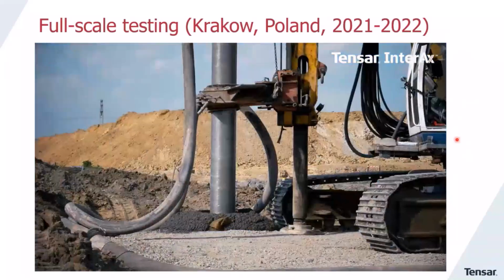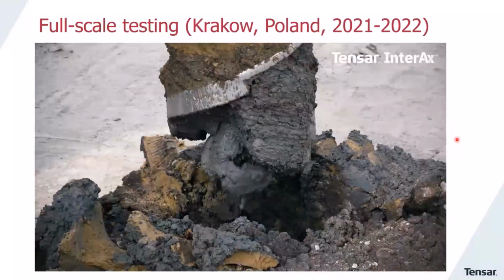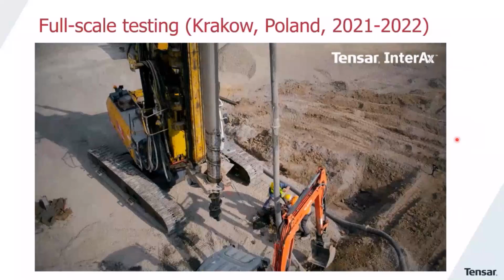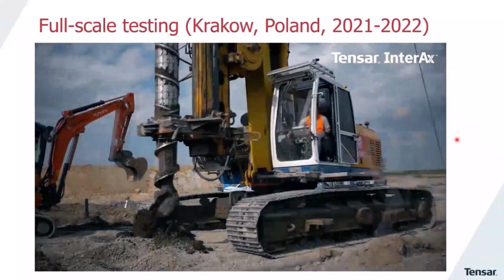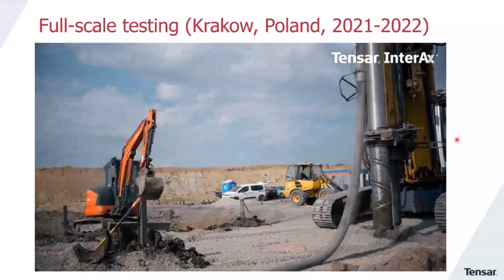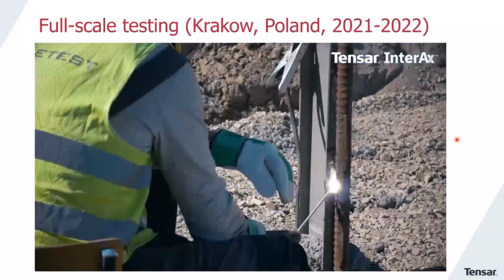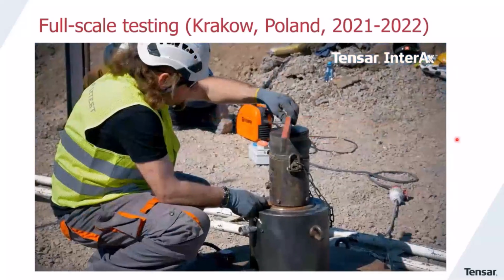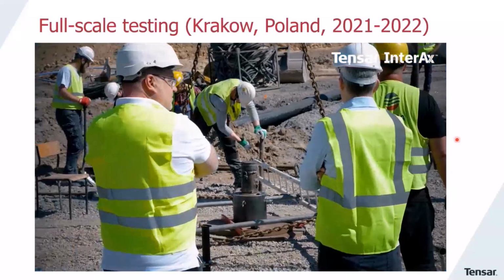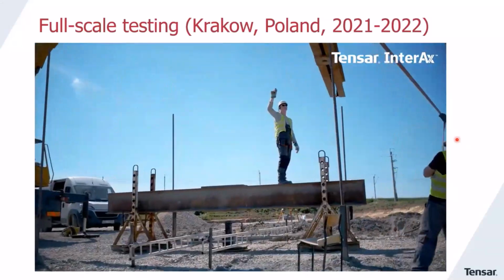And what we are seeing now is the drilling of 4 holes through the raft to be able to anchor the testing frame into the soil itself. The granular raft or the working platform is so strong that extreme loads are needed to even bring it to failure. And to be able to press so hard down on the working platform, this frame is going to be constructed to counterbalance a hydraulic jack pushing downward.